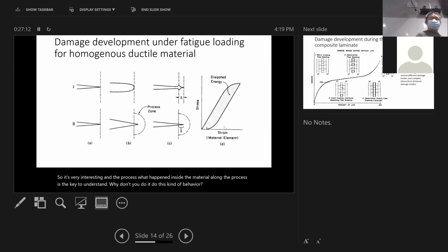All right, for metals, this is a schematic for the metal fatigue process. It's a single crack starting from a very small size comparable to the grain size. The grain is tenths of microns, usually a few microns. Starting at that scale, you have very small slip planes that grow into a crack. That crack keeps going to a microscopic size.